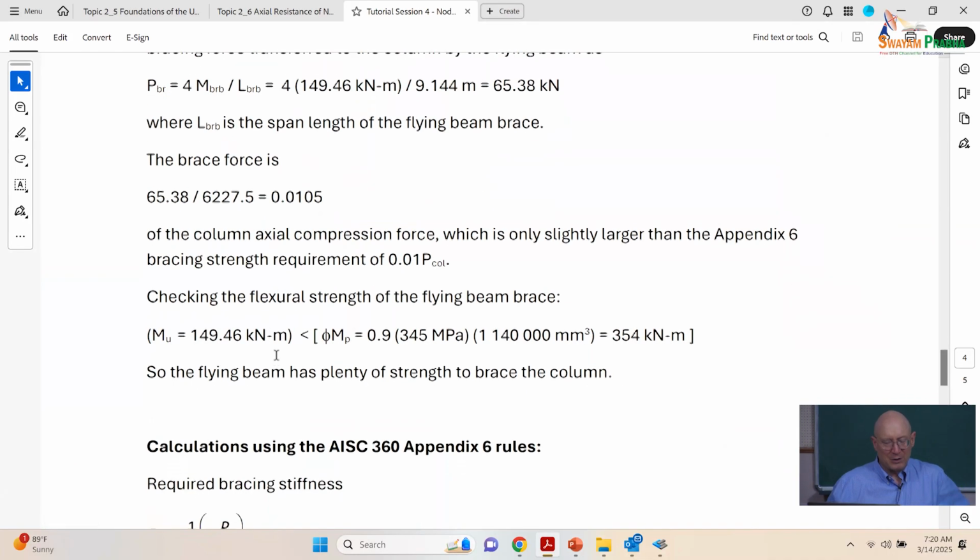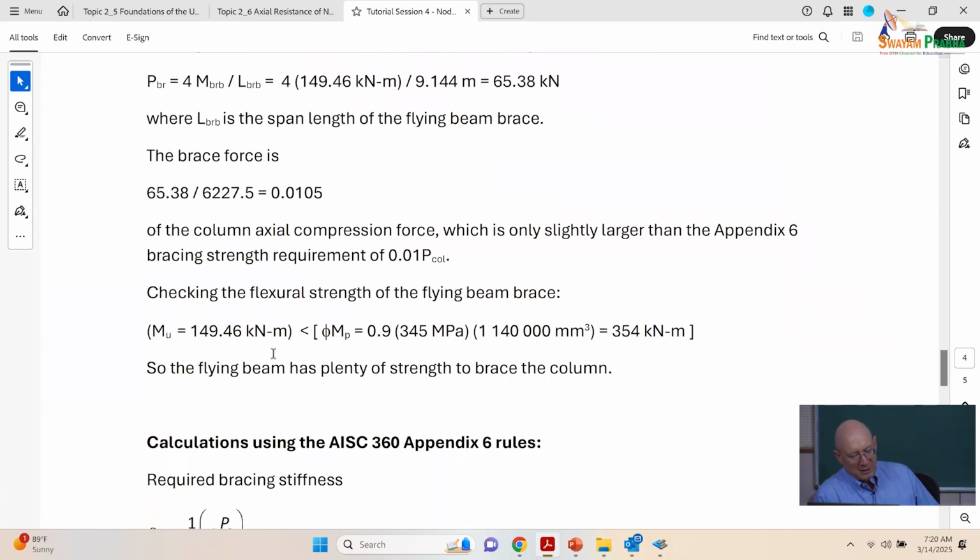I can consider the LP and LR of the flying beam and the CB I've got here, which is 1.75, and I can determine that when we scale the uniform bending strength by CB, for the unbraced length of basically 15 feet in the flying beam, the AISC beam flexural strength provisions tell me I can get plastic moment in that beam.